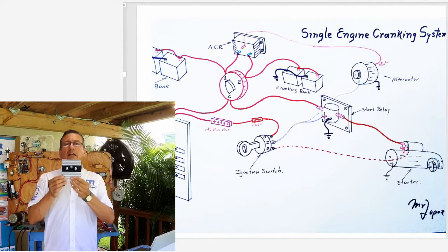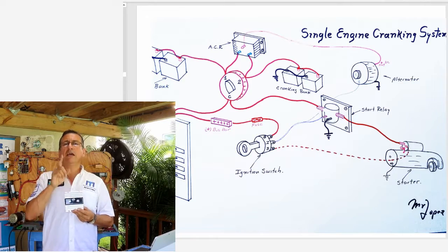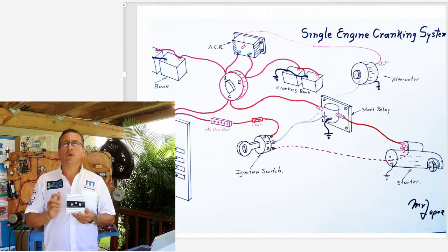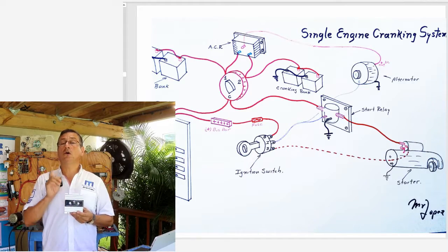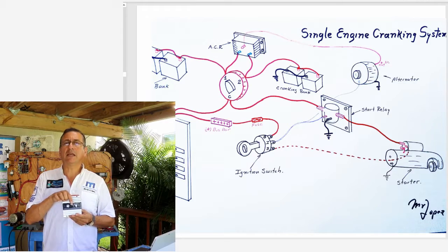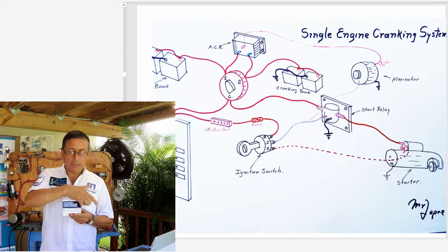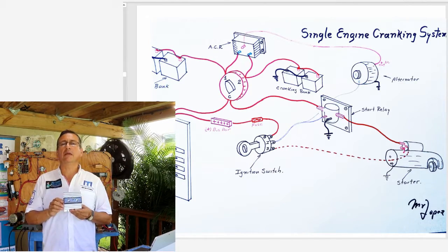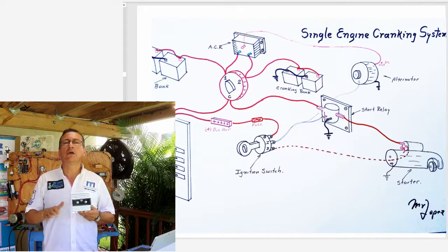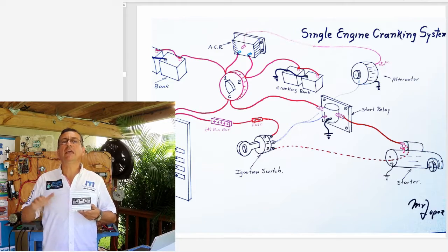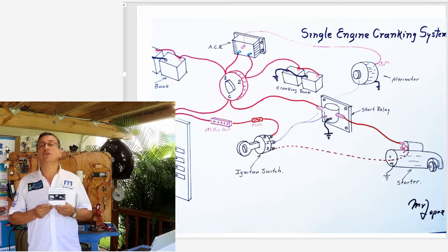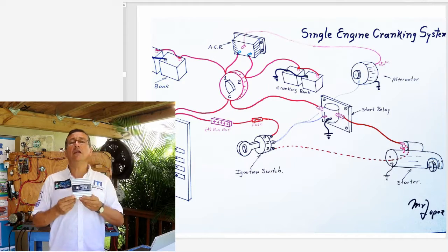And what is the idea? Suppose that I have a single engine boat onboard with one alternator. Okay, that alternator supplies power for both battery banks at the same time and keeps both banks with the same level of charge, equally charged. Oh, what is the recommendation if I use this ACR?